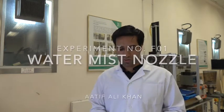I will be your lab instructor for experiment number 01, which is the investigation of the fire suppression mechanism of a water mist nozzle. What is a water mist suppression system? These systems are designed to suppress any pool fire, or any fire, which historically was done by halogenated systems. But halogenated systems are obsolete because of their environmental issues, especially their ozone depletion potentials. So these water mist nozzles are used with water as the suppression agent.